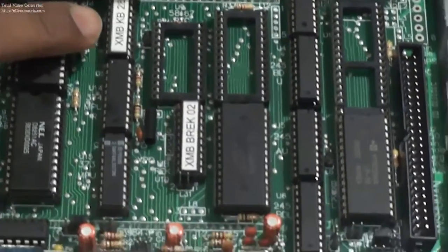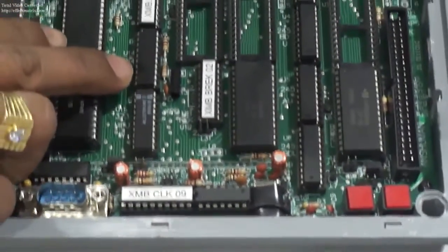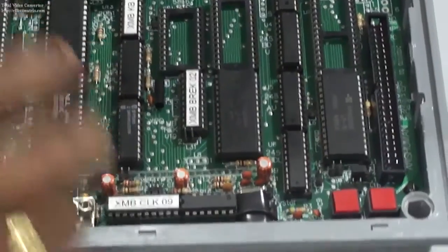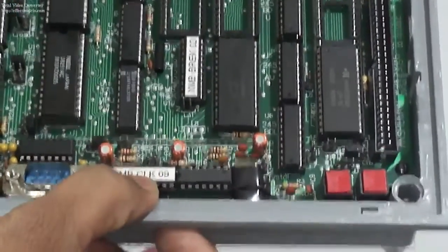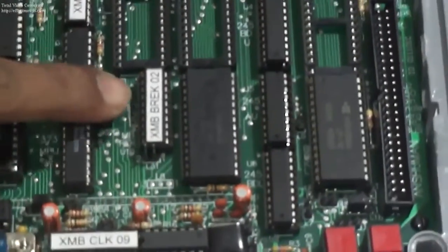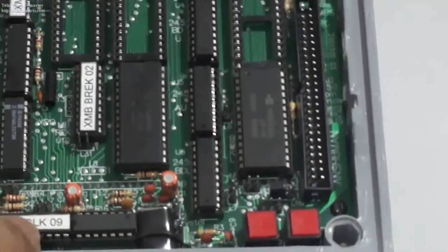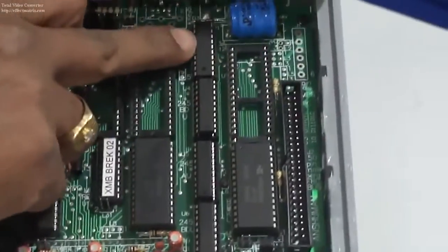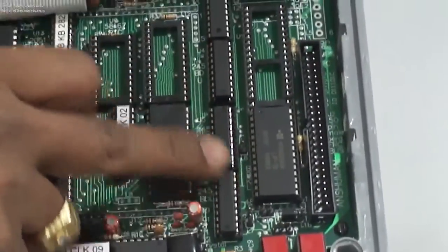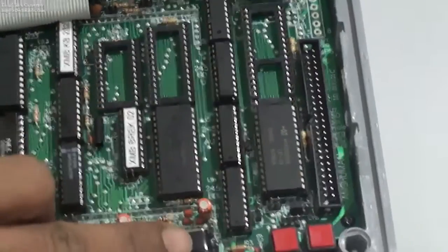Here we have provided the 89C2051 IC, which is mainly used for keyboard and display interfacing. The 74LS373 latch IC is provided here. The clock divider IC and PAL IC are provided here. NAND gate 7400 IC. This is the 6264 8KB scratch pad memory IC. Here we have provided an on-board 20 MHz clock, which is divided by using these clock ICs. The 74LS244 ICs here are all buffer ICs, address buffers and data buffers.